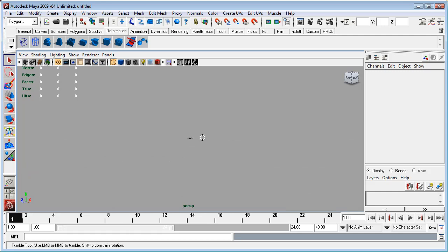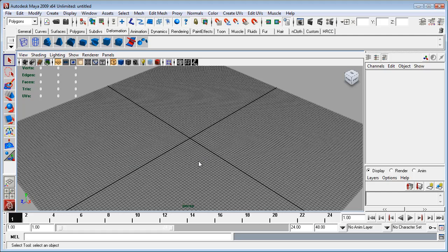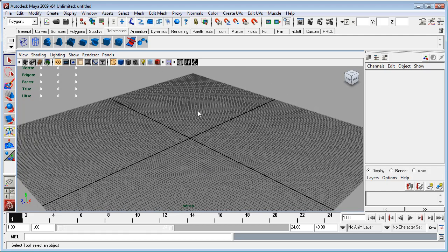And you'll see if I zoom out, that's the distance that our far clip plane is at the moment. If we don't set that, that popping out happens a lot closer to the origin point, and it can be very distracting and very difficult to create geometry that way.